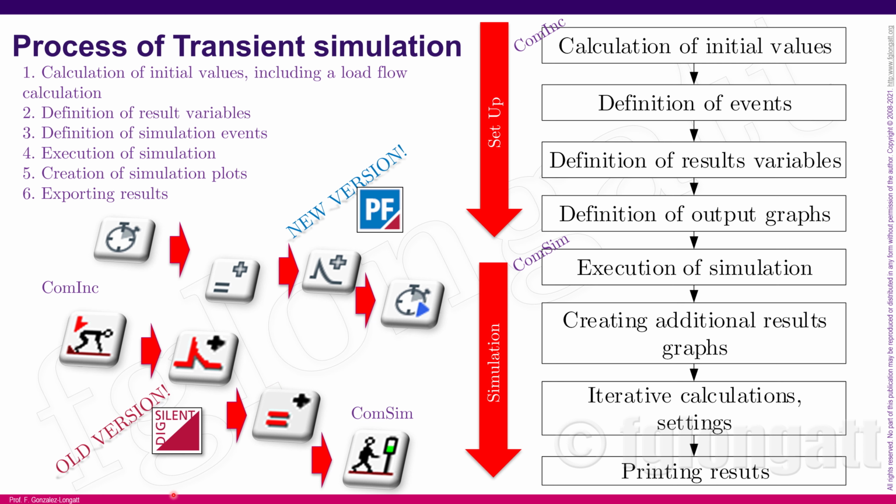To be honest, those four icons are the most important icons that you must be familiar with if you are interested in running dynamic simulations. They are essential, and you will be pressing them for long and many times. I highly suggest that you be familiar with them. Again, there are 4 icons: initial condition, defining events, adding result variables, and finally running the simulation. That is all.